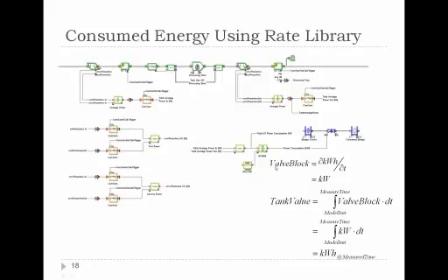To show the math, the valve block is a rate, so the kilowatt hours divided by time, so it'll be the kilowatts. We're going to input in kilowatts, and the tank value integrates the valve block over time, so we integrate from model init to measure time of the kilowatt times time, and we get kilowatt hours at the measured time.